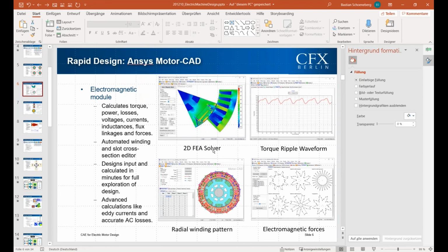But once we have these spray properties, for example, the particle size distribution, we can use this to create a particle injection region in CFX, and then we can have a look at where the oil goes.